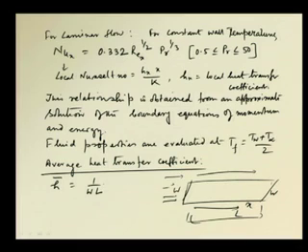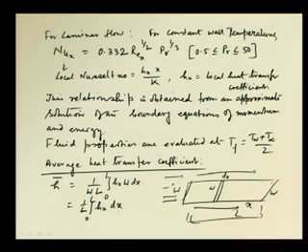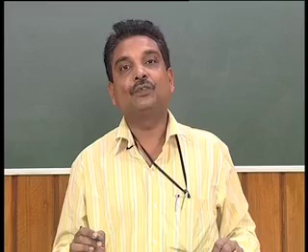Okay. So, therefore, h bar is equal to the integration from 0 to L of hx into W into dx, because for any differential strip, if we do the integration, this becomes dx and this becomes W. So, the differential area in this region is W into dx, and this W cancels. So, our integration limit will be from 0 to L. Therefore, it becomes 1 by L, integral 0 to L, hx into dx. So, this is the expression that is used to find out the values of average heat transfer coefficient.